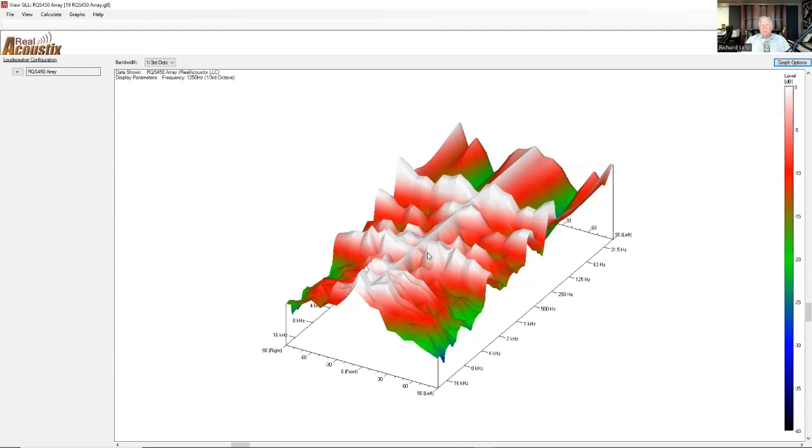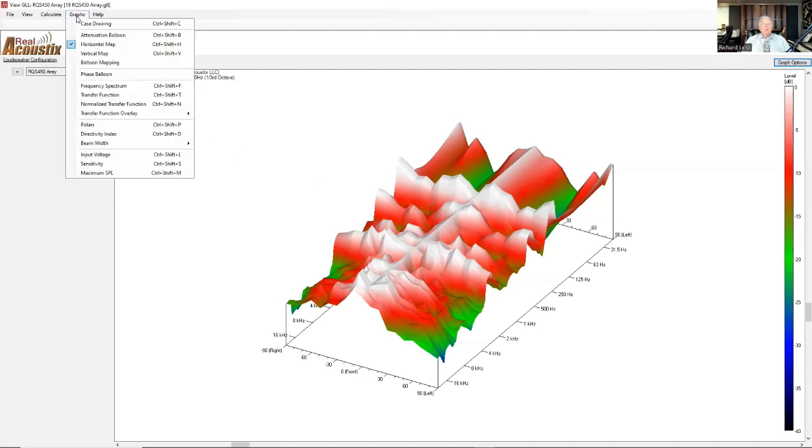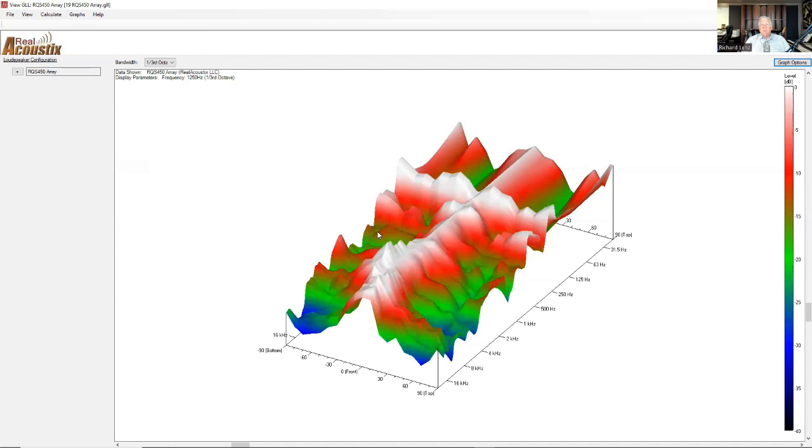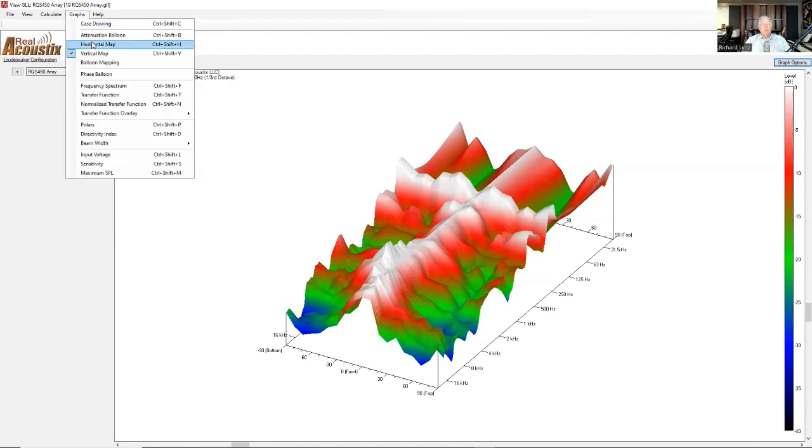But again, that's a very narrow plane. This is really its operational range, what we consider its operational range, which would be somewhere between about 1250 and 4K. But again, there's still going to be operational range, just much more directional when you get up there. You can do the same thing looking at the vertical plane. And with a 1D, this is especially obvious that there is very little vertical dispersion at all, and it's small there.